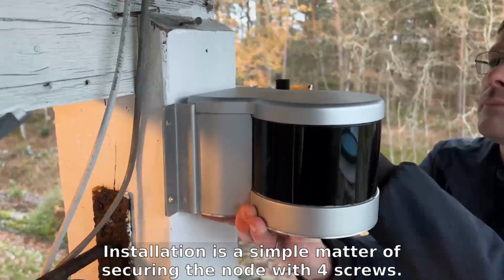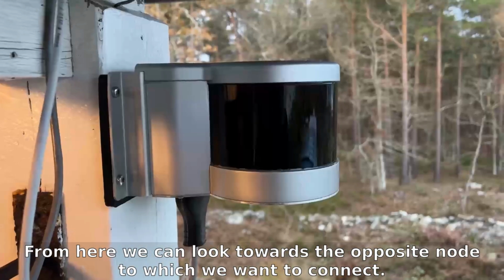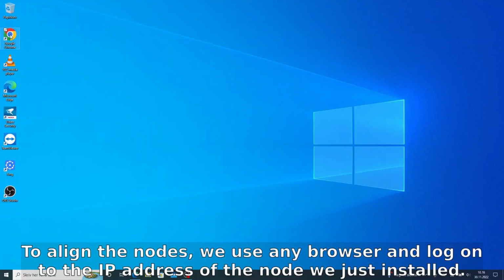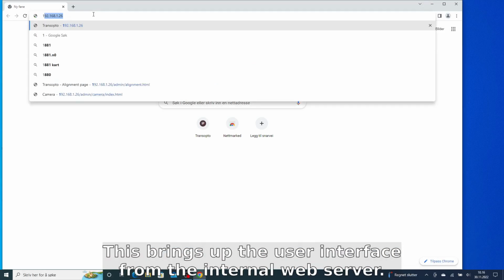Installation is a simple matter of securing the node with 4 screws. From here, we can look towards the opposite node to which we want to connect. We will do this by logging on to the management interface. To align the nodes, use any browser and log on to the IP address of the node we just installed. This brings up the user interface from the internal web server.